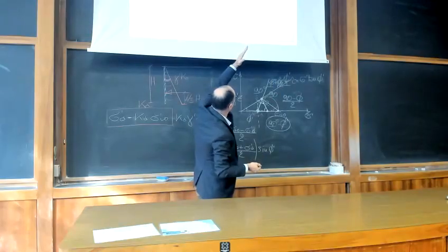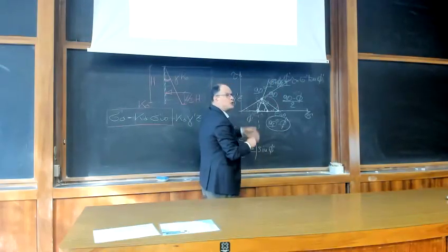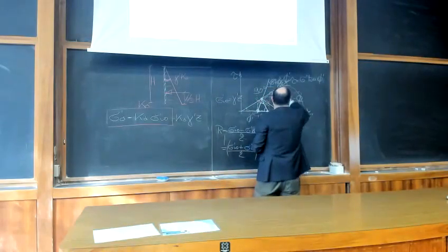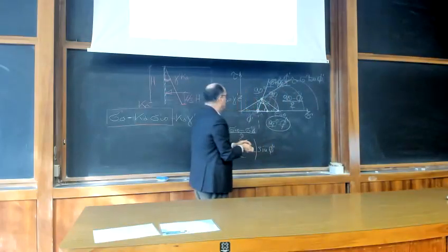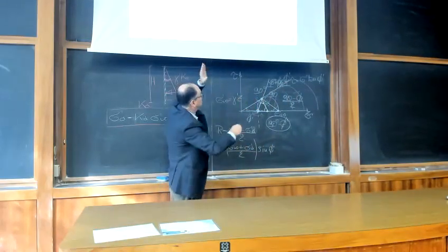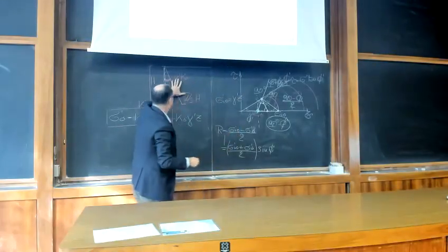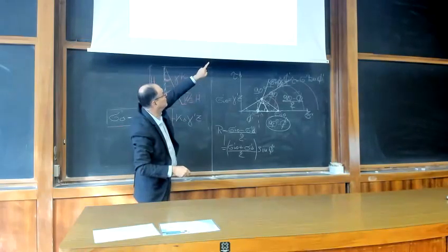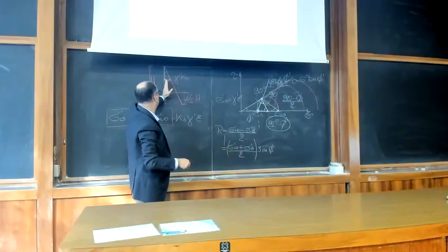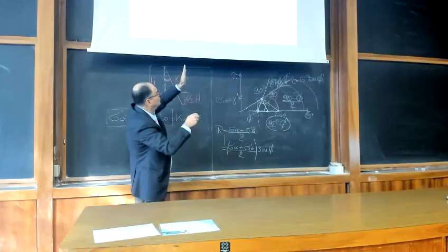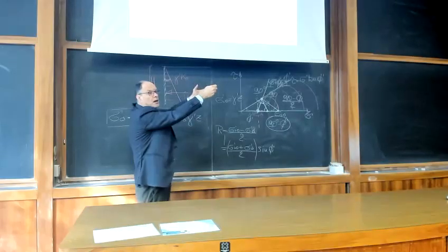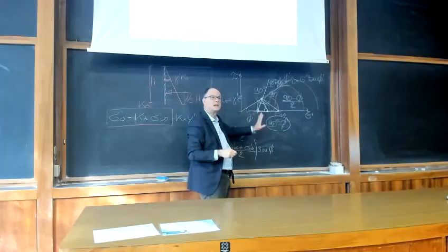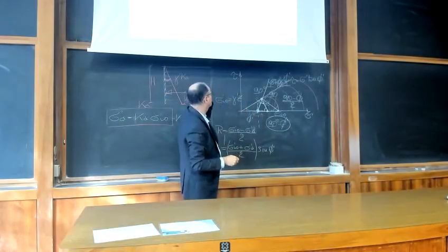So if you plot your slip planes, they refer to all circles, because you have plenty of circles like that. Any time you increase your vertical stress, increasing your Z, you have a lot of circles, you have different planes. So all these parts become failed along these slip planes, and then if the wall moves laterally, the soil slides along these slip planes and moves laterally, without further decreasing your horizontal stress, because this is the limit, the minimum possible value.